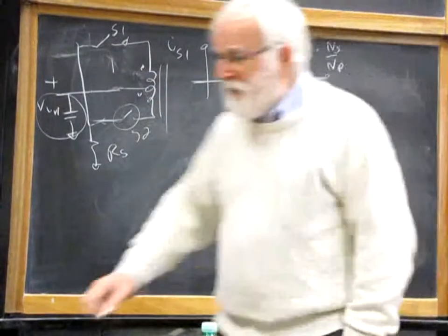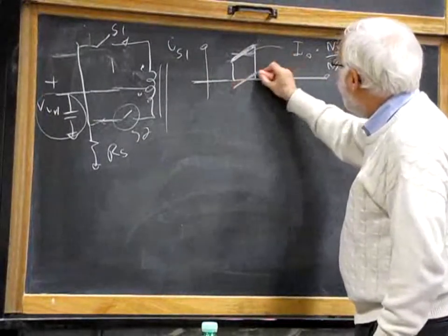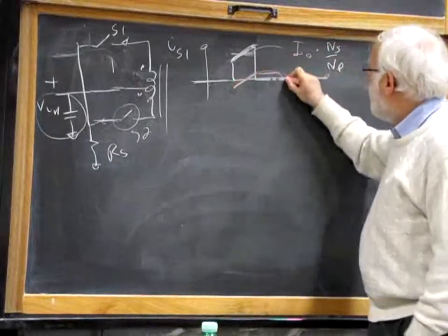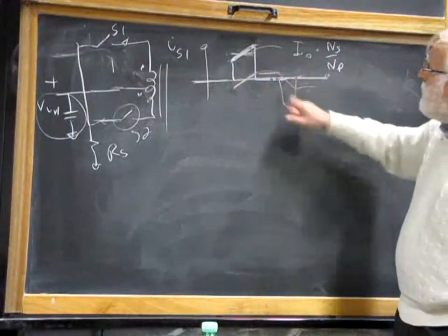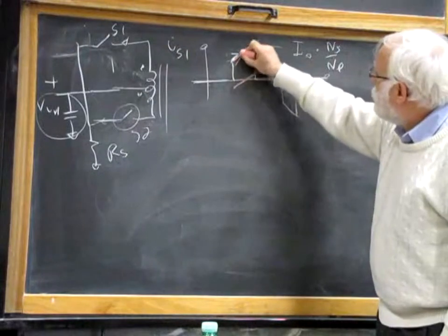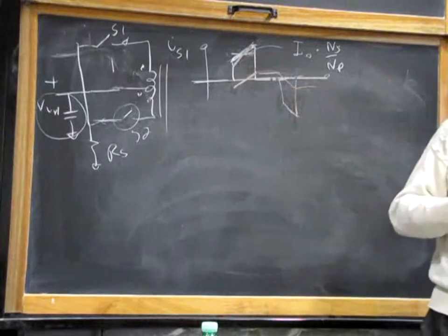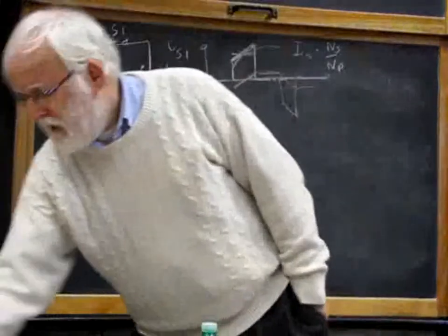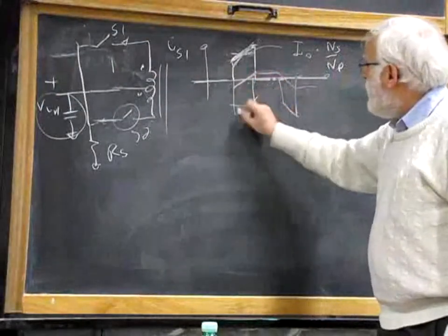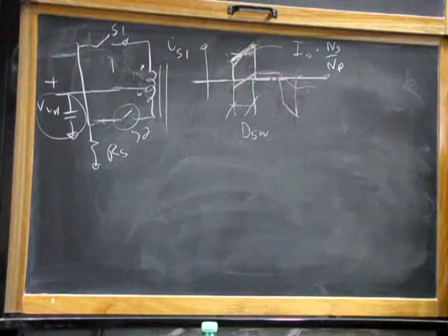And on top of this current on the primary side, there is also a magnetizing current. The magnetizing current is something like this. It will have the effect of increasing a little bit the slope of this ramp. Okay, it's not so important for the stresses. This current pulse has a duration that is this width. And now you can find whatever you want from this waveform.